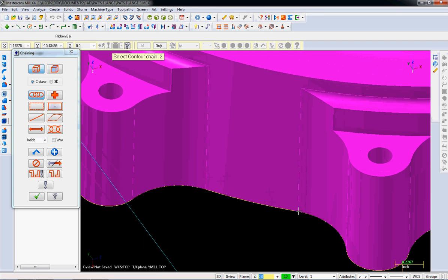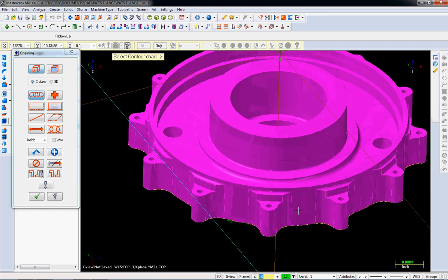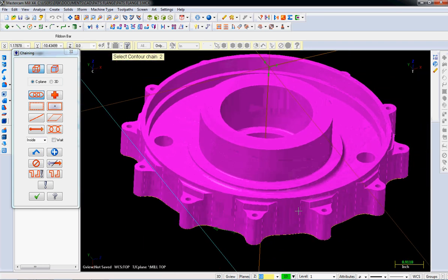Even though in Mastercam you've got these solids all over the place frequently, you're doing what's not a solid operation. A contour doesn't know about all this stuff out there. It knows about this one chain. That's it. It doesn't know anything else about the chain, and it's just as valid to contour on the inside as it is the outside. So think about a climb mill and make sure the cutter's on the right side.